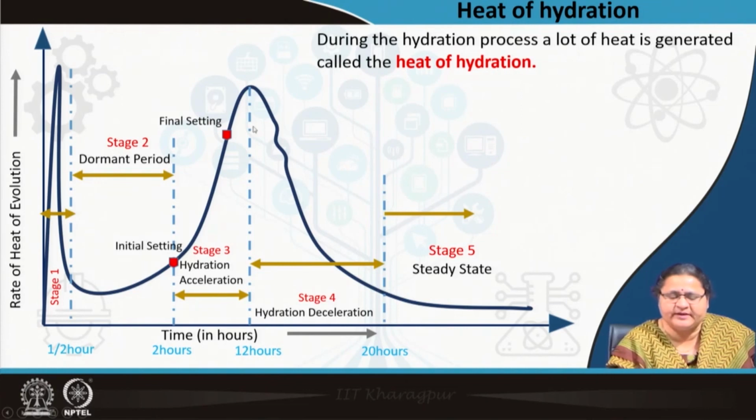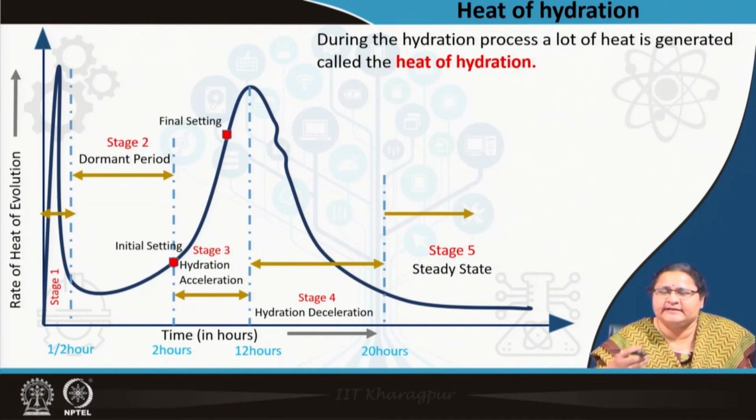So, in these two time periods, this amount of heat is liberated, and if this heat is not gradually taken out, it may lead to finer cracks inside. So, these points are to be remembered. Hence, whenever concrete is done, it is kept moist and also in contact with air, and it gradually cools down. That helps. This gradual process of heat liberation is also to be controlled so that you do not end up with cracks. So, this is the heat of hydration.